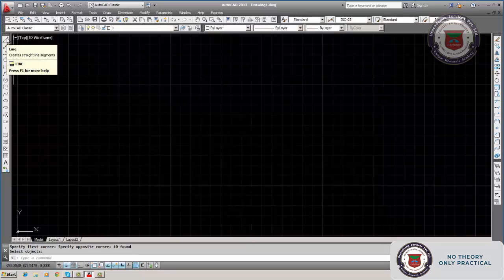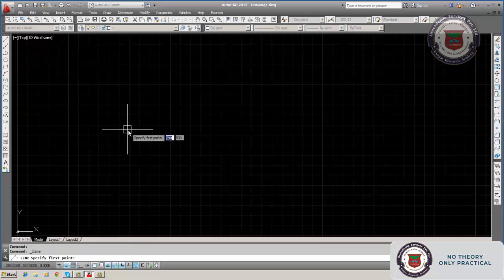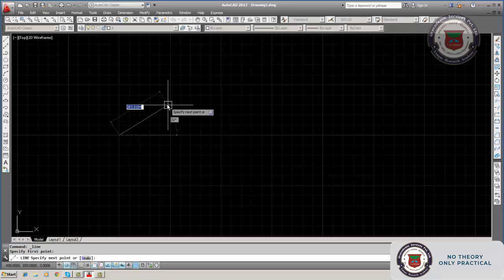Now suppose we want to draw a line here. Click here as usual. But here it picks up wrong points. You can't have any fraction point. It will be in multiples of 10, as we set it. You can pick up 250, or you can pick up 290, 340, like that in tens. Suppose I pick up 250. Click here, and if you want to draw any fractional line, not in multiples of 10, then you have to enter the values here and the angle also.